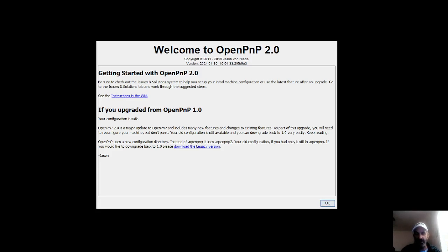If you don't know how to do that, and I will tell you it is certainly a steep learning curve for those who are not familiar with GitHub, you should really consider putting some time into that, because it makes backing up, going backward, if you've messed something up in your machine.xml, so much easier. And there are even some crafty ways to run two copies of OpenPnP at the same time. One so you can reference what you did in the earlier copy or some master copy, and one that you're trying to modify as you go.